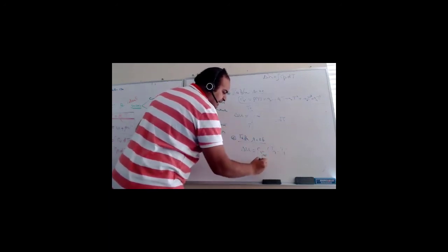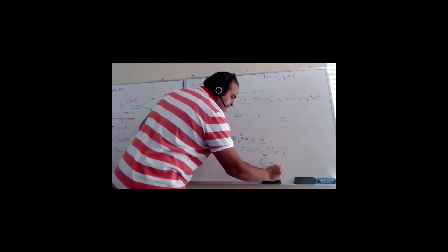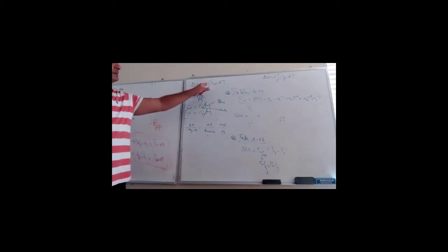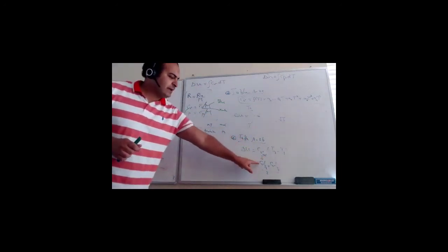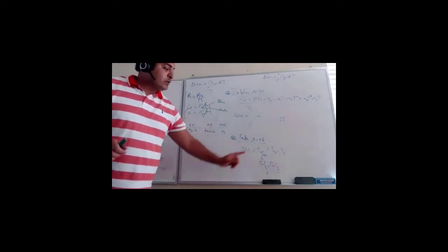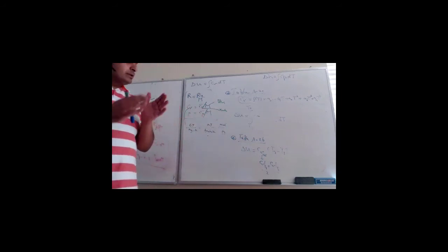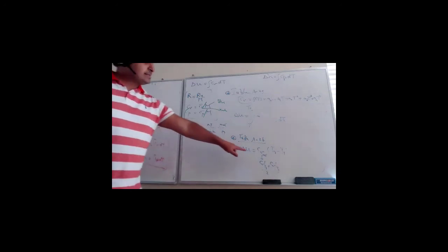And CV average is CV at T2 plus CV at T1 divided by 2. So you can simplify. Take CV out of the bracket, integrate delta T, just change the temperature. So it's just CV average like this. And this CV average can be CV average or CV at room temperature, as you wish. So the lower the temperature difference between T1 and T2, and at lower pressure, the better this approximation is.